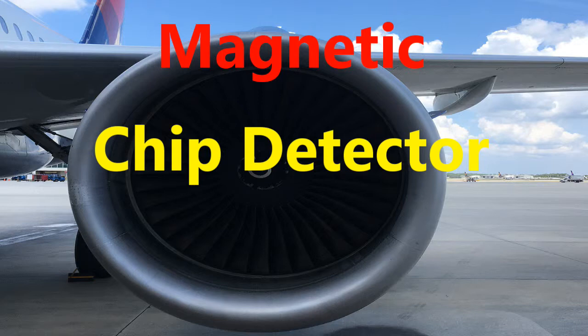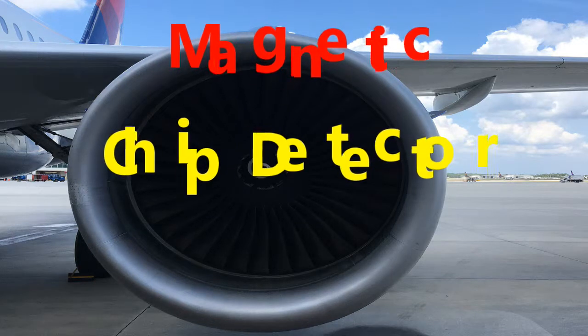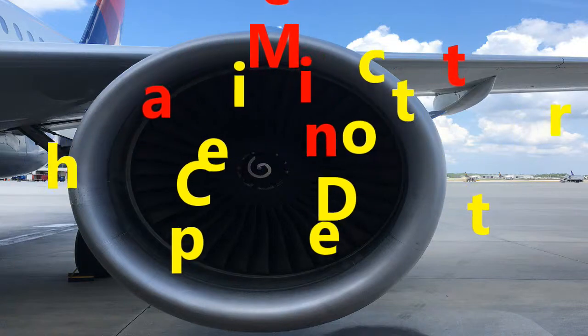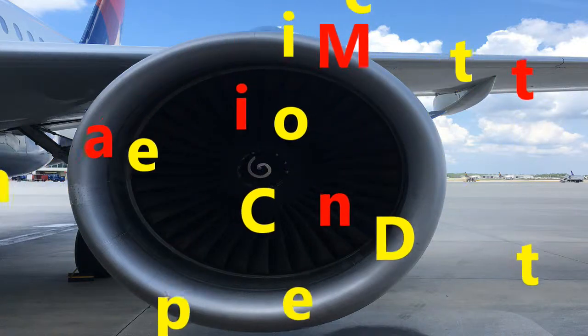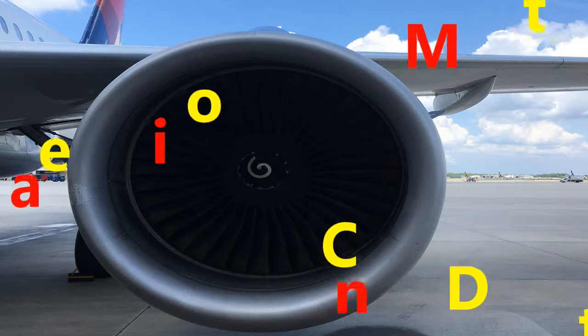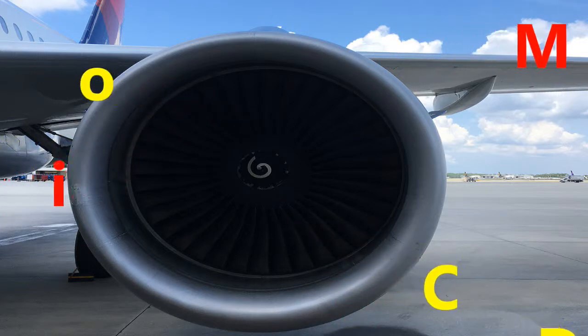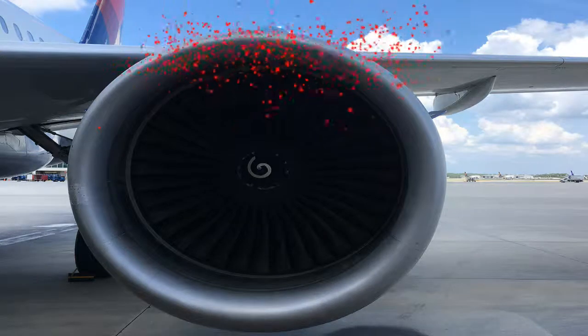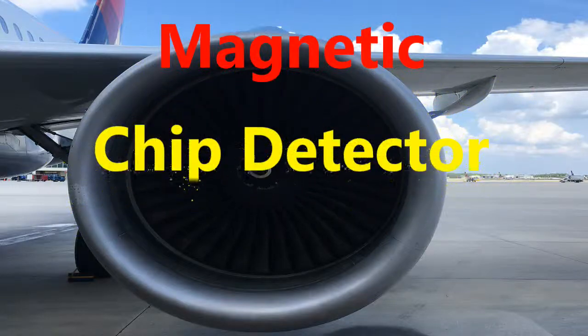Just also a little bit of description on the spool. That spool is installed in a bore of the lubrication unit housing, so that's where you'll find that. And as far as the magnetic plug assembly itself, when you remove it, the spring is going to push the spool into the sleeve. That's just the way the mechanism is.